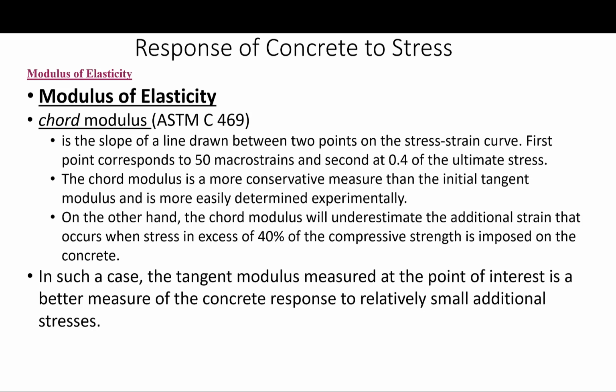The initial tangent modulus or the secant modulus are not always easily determined because of errors in the measurement, due to specimen seating at the initiation of the test, or due to the existence of pre-existing cracks that close up under applied load.